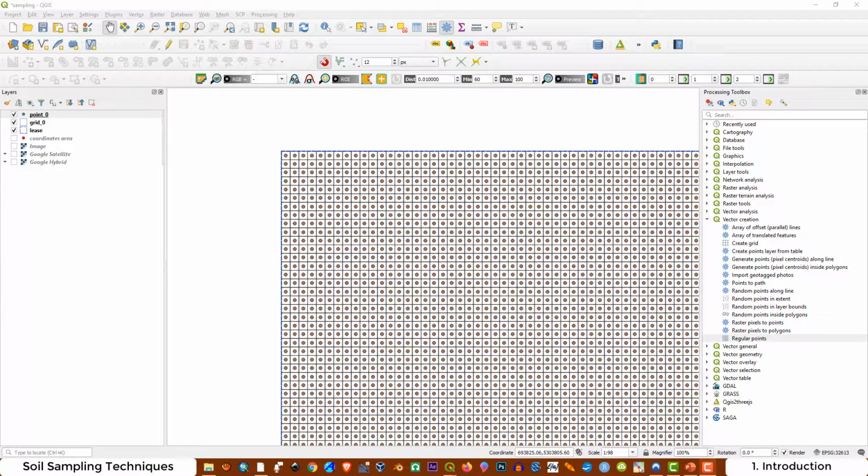Then when we are doing a study in a site that is contaminated, we have to think in the same way. What is the potential population in our site, and what could be the representative samples that we want to take from that population? In addition, we have to think that the soil samples are distributed spatially. It's not just in 2 dimensions like X and Y. The soils are also located at the Z axis. Let me show you in a graph.